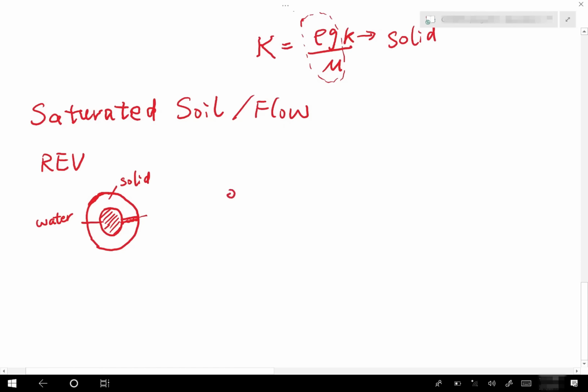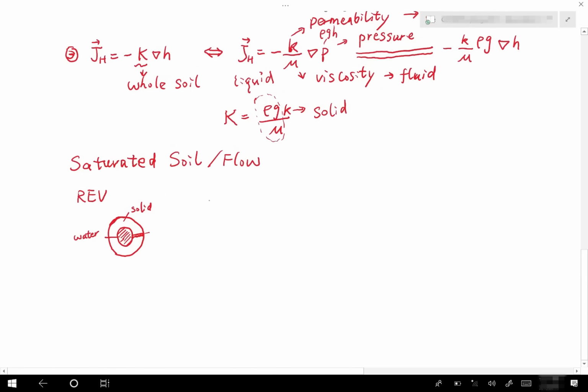So the general equation says, zoom out a little bit. It's partial something, partial t, so the change of something over a limited time equals the divergence of the flux. In this case, we use H. We showed how to derive it. This is the final differential form. We started from the very beginning, right? We talked about how to move through the boundary, and then use Gauss's law. We can convert a boundary integral to a volume integral, and eventually we get this divergence term. We showed how to do that. Do you guys still remember?